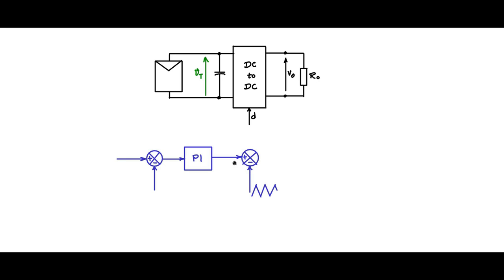So when the DC signal and the triangular carrier are compared, the output of the comparator would be a pulse width modulated signal, and that output is what is given to the D input. The D input internally will drive the power semiconductor switch within the DC-DC converter. So this would be the schema. Now we need to see what are the values that you need to give and what variable you would want to give here. Now let us go back to the voltage scaling rule which we just now discussed.